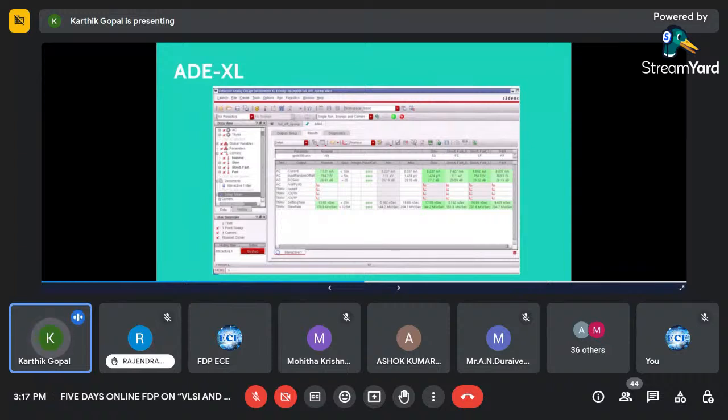So in that 12-inch wafer, if you take the chip from the center, that is called the typical. If you go towards the edge, the performance of the MOSFET differs. That we call corners. For example, if you take a piece of a cake and cut at the center, it will have a white colored one inside. If you take it at the end, you get either cream or a baked one, right?